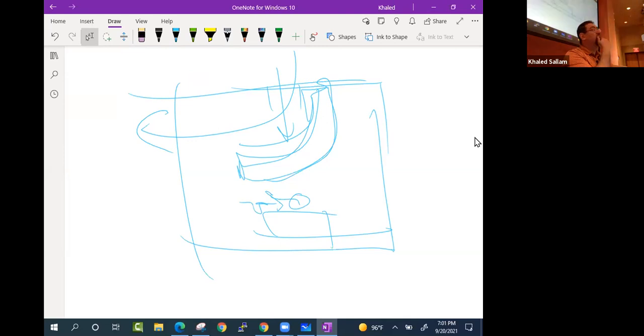So anyway, for this project, we will go through it in a minute, and I don't really need you to optimize it. If we needed to optimize the solution, I would have said you definitely need CoolProp. But I realize CoolProp is annoying to install, so the way the project reads right now is: run 3 different refrigerants at any property and test condition you pick, and then in task 4, make it more accurate by adding superheat. At no place did I say find the optimum design.